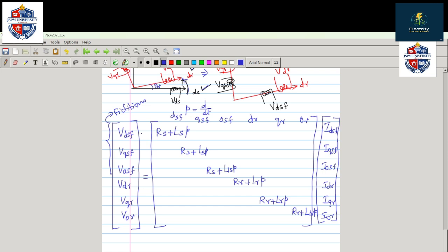In the last session, when I explained the observation method in the stator attached reference frame, I already told you that if two fictitious windings are perpendicular, there is a speed EMF term. So now these three windings are fictitious, and if two windings are perpendicular, we will have a speed EMF.